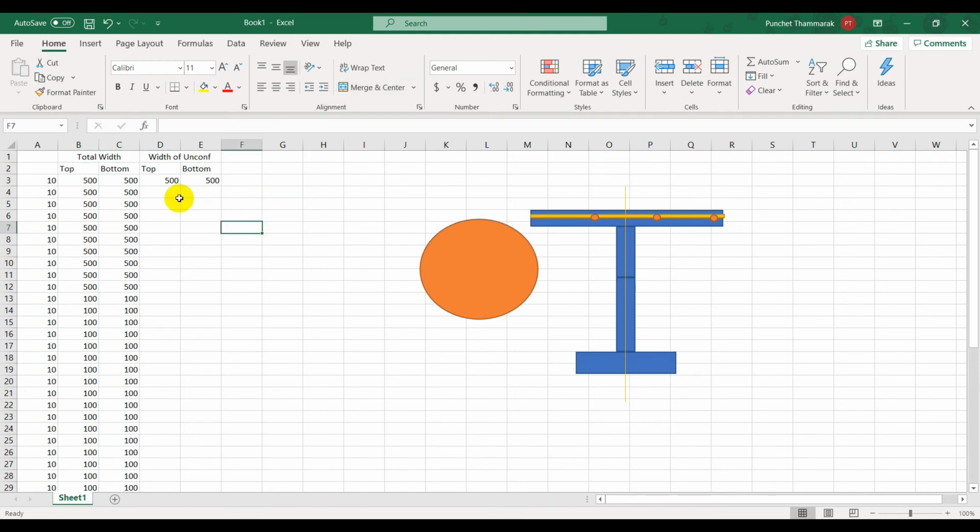Okay. So in this case, I think we might have the top two layers being unconfined concrete, because it is the covering, you don't have the stirrup. And then unconfined concrete, once you are below 2 centimeters, it is encased inside the confinement.